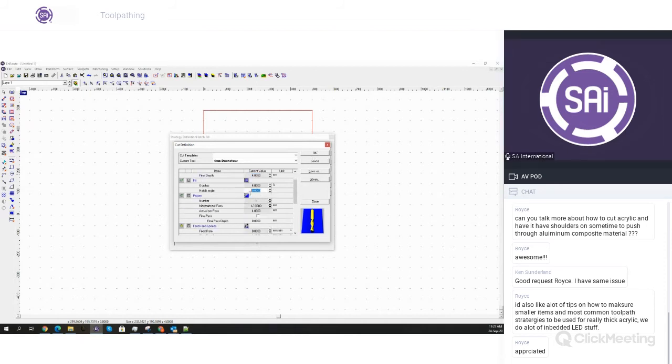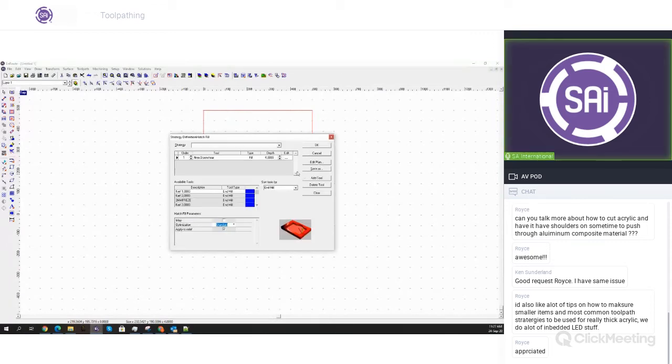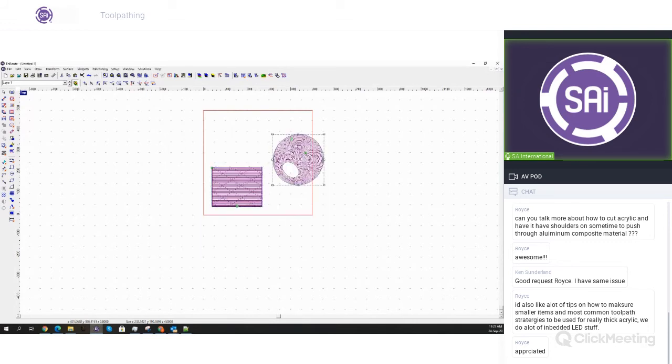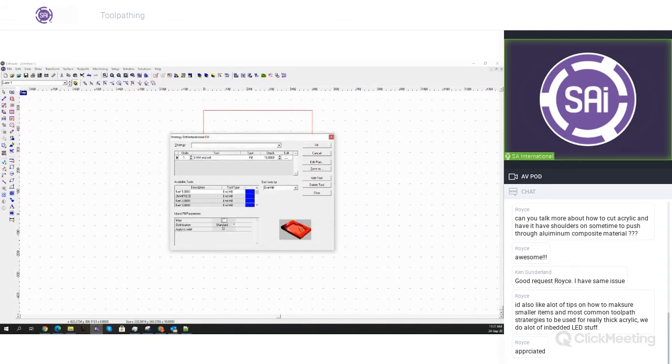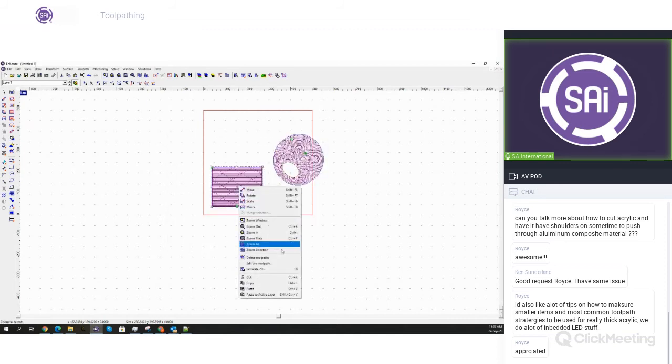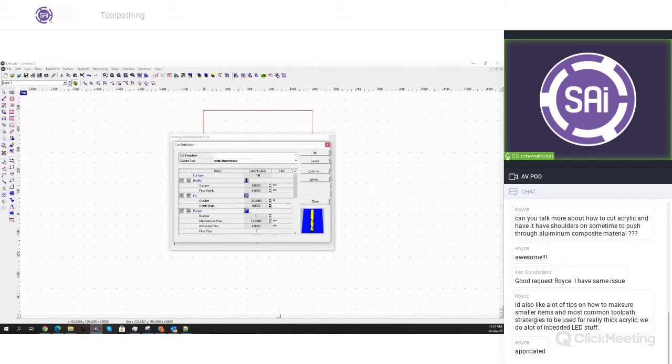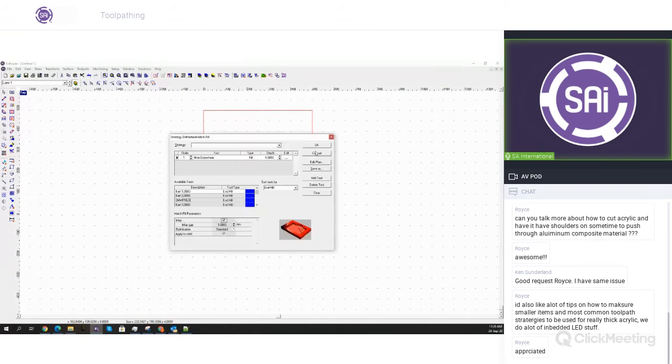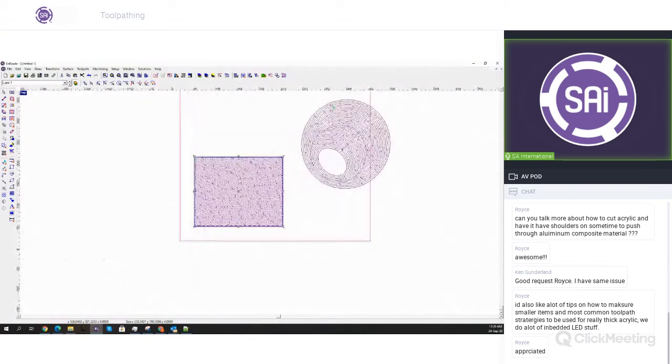As far as the other parameters here, they're the same as the routing offset. And for the island fill, they're going to be typically the same as well. So in here, you'll have mostly the same parameters as the routing offset as well. One more thing for the hatch fill, you can see that you do have the possibility here to set up a hatch angle if you would like to do that for some reason. So you could change the degree of the tool pathing like this, for example.